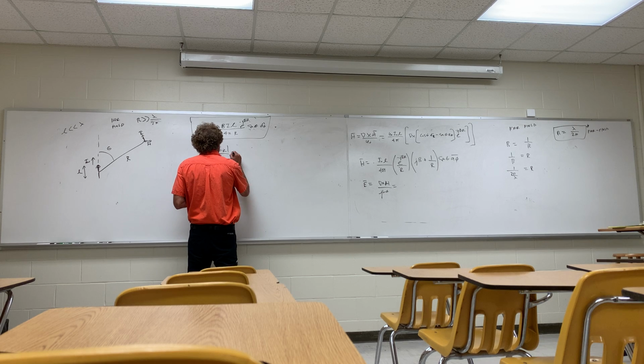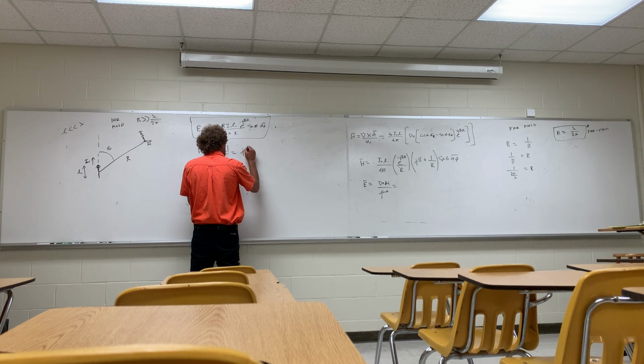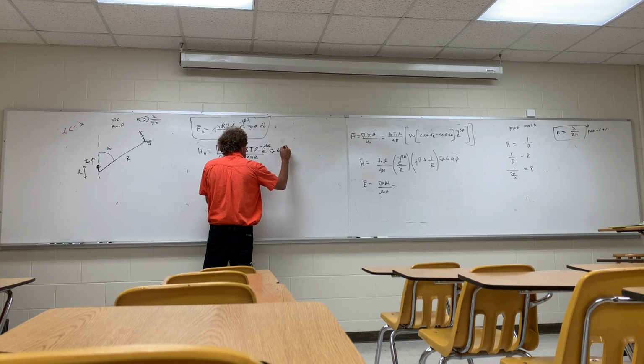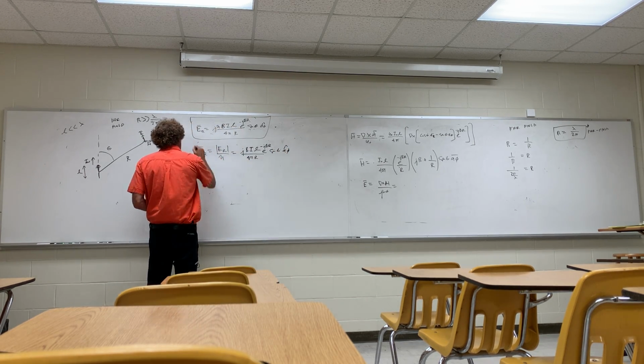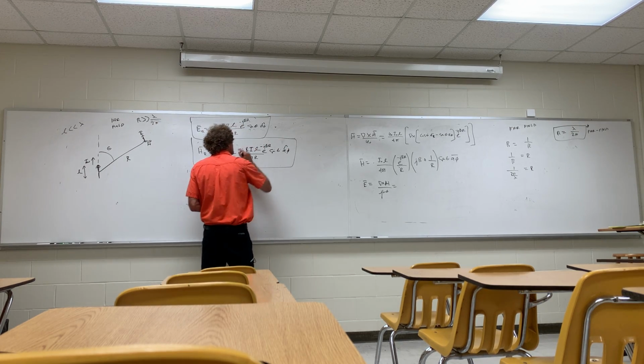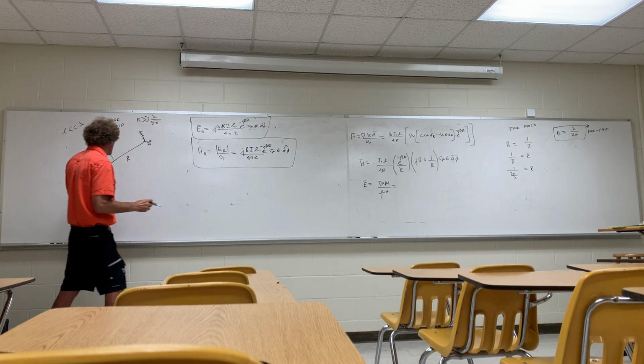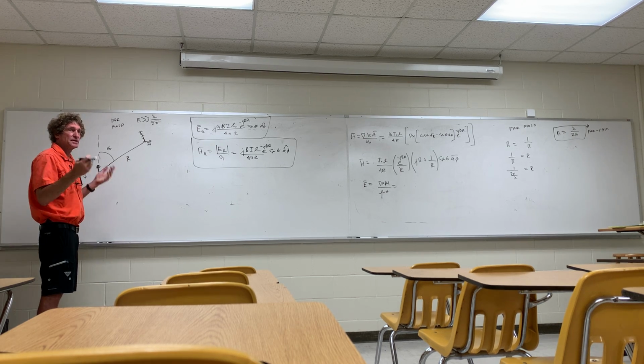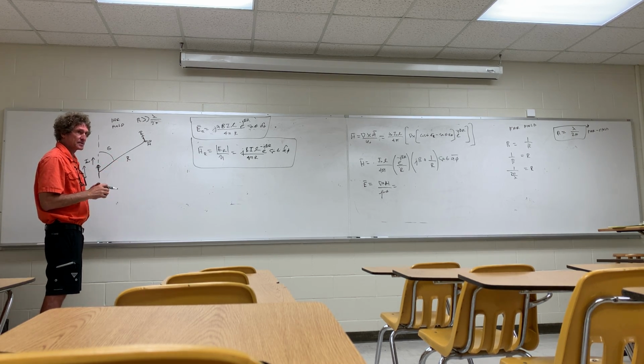This becomes simply j beta I L over 4 pi R e to the minus j beta R sine theta in the a phi direction. And it's important to understand these are the radiated components for E and H for a vertically oriented short dipole. And this is sort of the traditional point where you start with antennas.